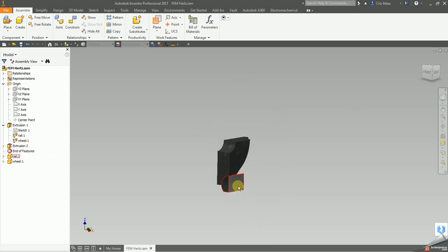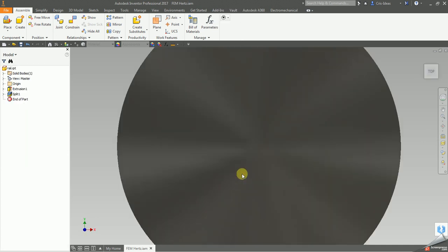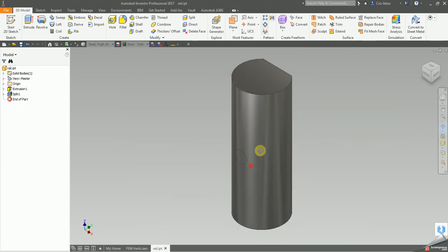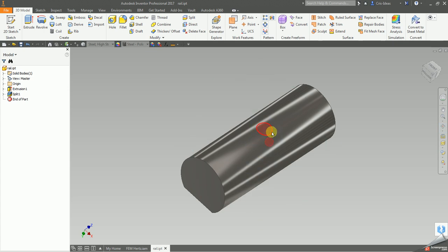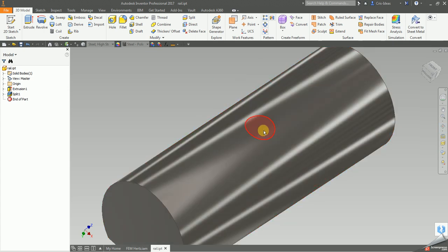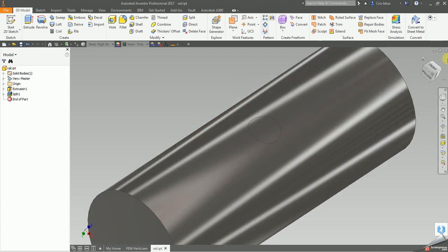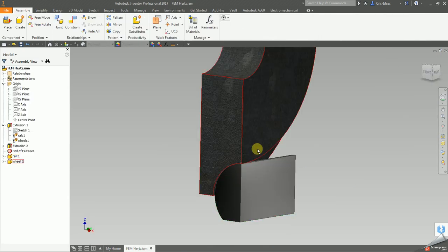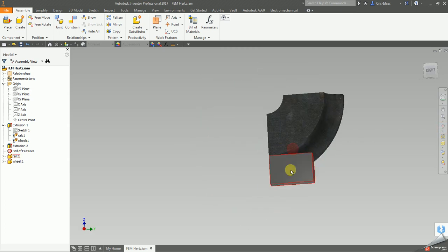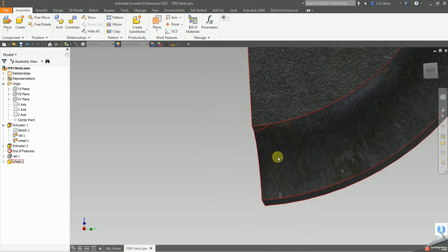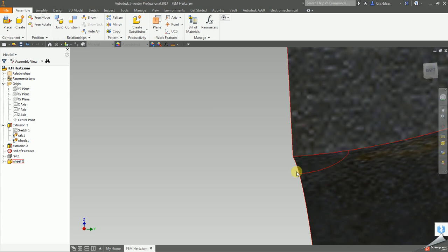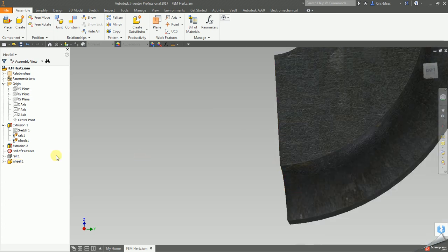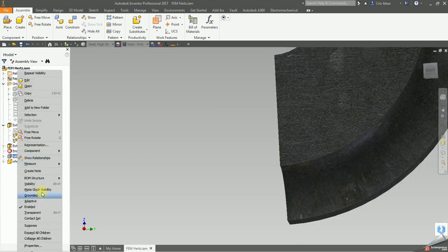What I also did is I have split the surface of the rail in the proximity of the connection at the tangent point, and I did the same with the roller. So close to the touch at the tangent point, I have an area here, and the same on the rail.